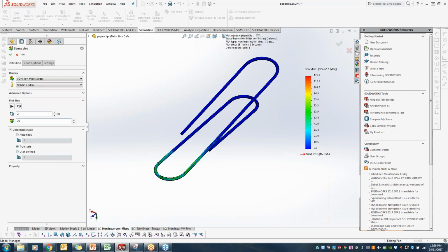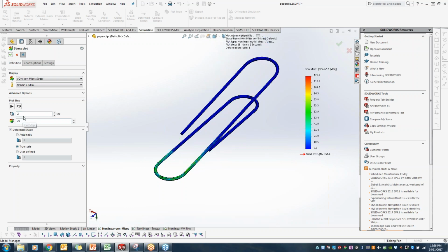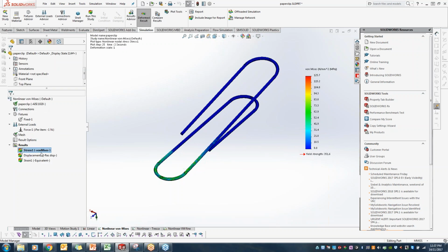The second difference we can see, you can plot your stress at any time step. 1 is the end of the loading. So this is the stress. Yielded, yes, past the yield point 389. This is the real stress value. I can look at the residual stress if I go to the second stage. So the residual stress here is 125.7 megapascal. So that is how much residual we have.